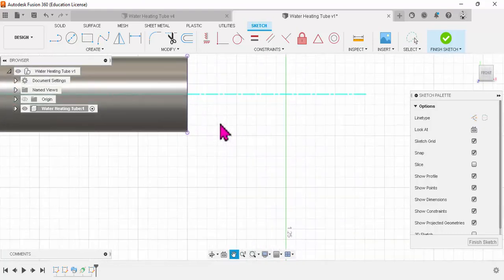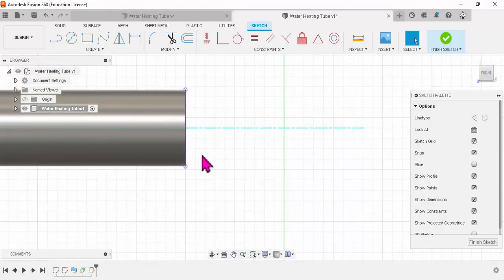So now our sketch plane is recognizing this edge, and there is technically a completed line from one point to the other point. So the very, very top of the cylinder to the very, very bottom. All right, so we can use that to create our closed profile so that we can later revolve it for our taper.